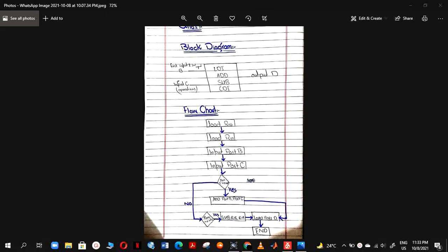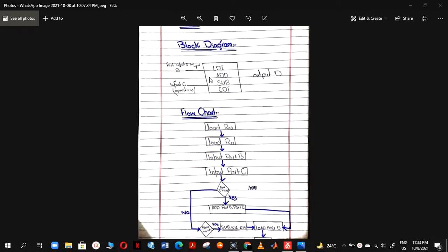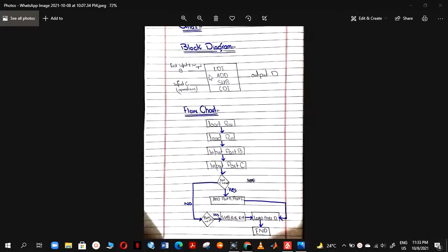First of all, we have to construct a block diagram and then its flow chart, how it works, and then we have to write an assembly code which we will run through Atmel or other software to generate its hex file, which we will import into the simulation, and then we check our simulation working. After all of it, we have to implement it on the hardware as well, in our labs or in our practical life. First of all, we are going to discuss its block diagram.